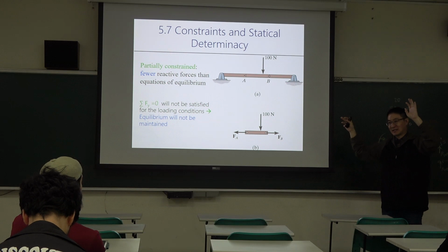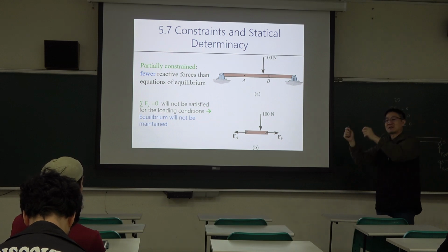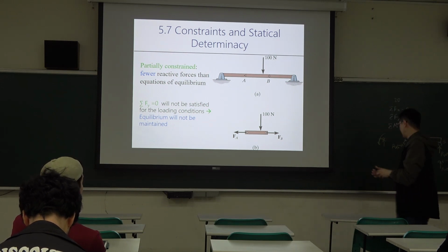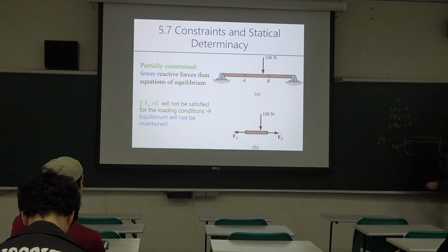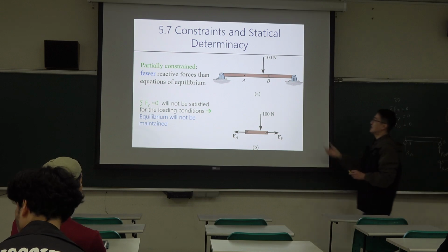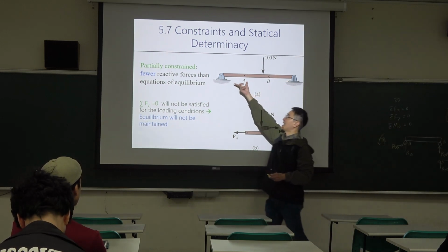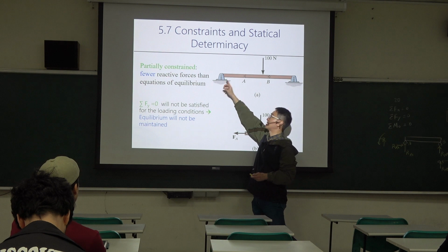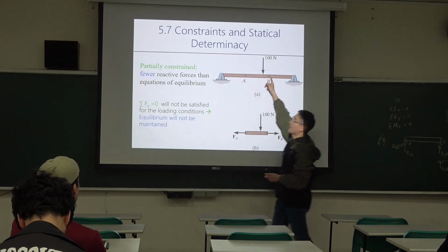So for a two force member, that's the element, the force must be along this line, and their magnitudes are the same and in opposite directions. That's called a two force member. So actually, this element and this element are two force members because they only have a point here, a point here.